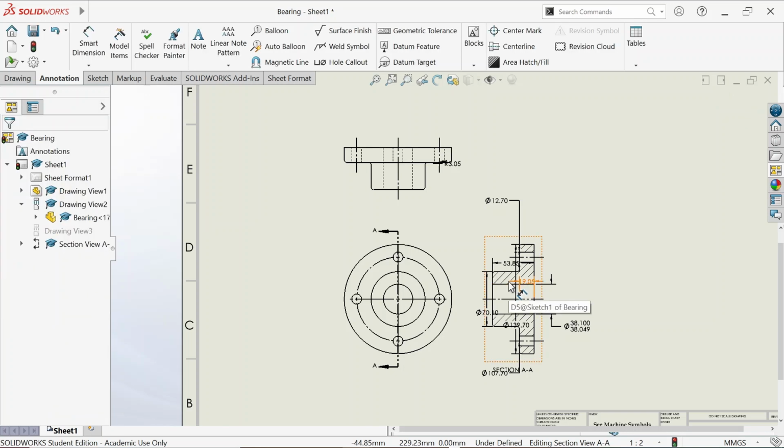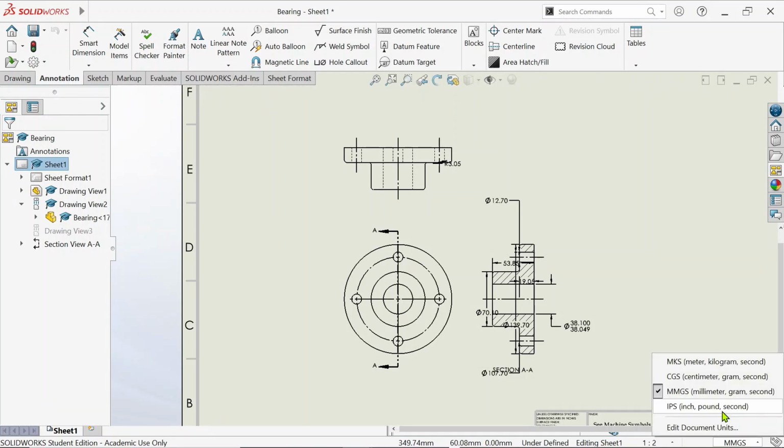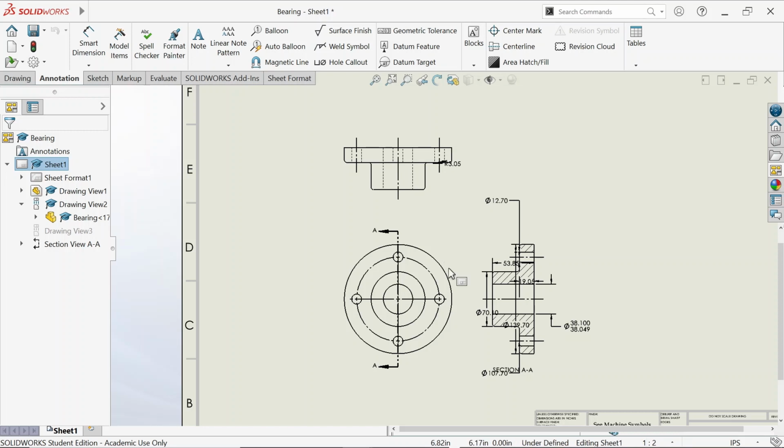These dimensions were used in making the 3D part file. These are being shown as a converted value in millimeters. So we switch to an inch system. Change the units from the bottom of the screen. You have got inch as the units. We find the numbers getting updated to the values as was provided in inches to make this 3D part.